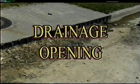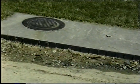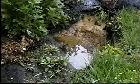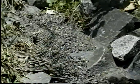Is debris accumulation impeding water flow substantially? Does the particular drainage structure require excessive debris maintenance? Is there evidence of substantial soil erosion around the opening? If there is, would the installation of a concrete apron, riprap, or relocation or reorientation of the opening correct the problem? Is the opening flush with the surrounding terrain features, or does it constitute a pocket that could trap a vehicle? If the opening is inclined, could it cause vehicle ramping?